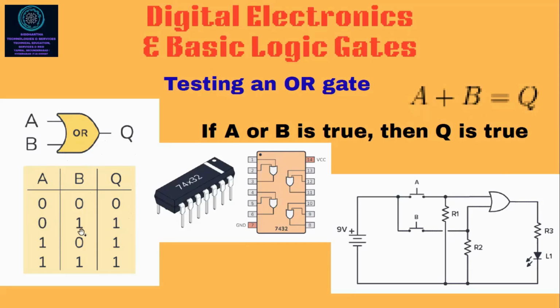If one of them is 1, please remember, the output Q will be high. That is, if A or B is true, then the output Q will be true. So in this case we get 3 high outputs, whenever there is 0 and 1, 1 and 0, and 1 and 1. If A and B are both 0, the output will be 0.